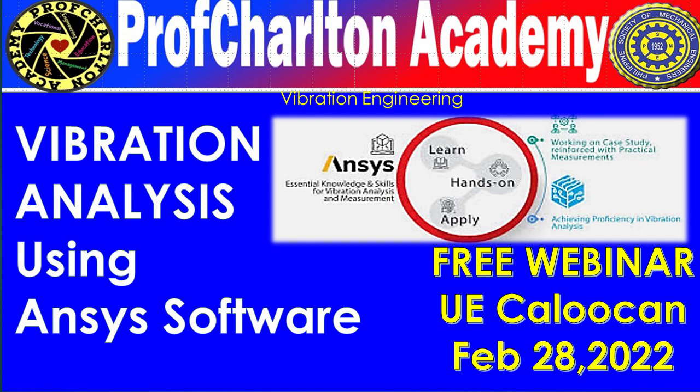Okay, so this is the Workbench platform that I was mentioning before. Workbench is the simulation platform of ANSYS. In the Workbench platform, on the left-hand side, we have a lot of analysis systems. These analysis systems are designed for a particular type of analysis. For example, let's say we want to do an FEA strength analysis. For the strength analysis, we have static structural. You can click, drag, and drop it over here.